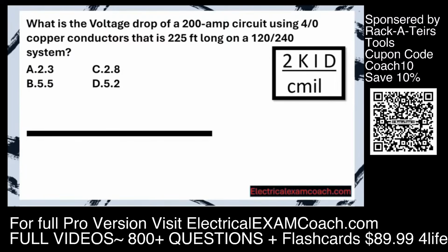Let's start with 2. Is this a single phase or a three-phase service? Well, this one is single phase, so it is going to be 2. Then I like to go ahead and put my X down for multiplication so I don't get my numbers mixed up. Then let's go to the K, and that's going to be dependent on the type of conductor.